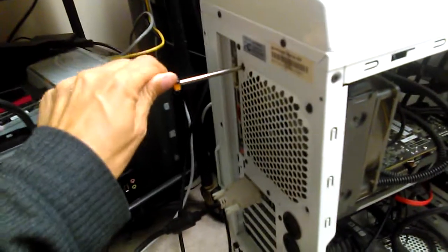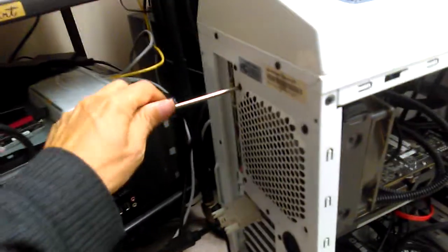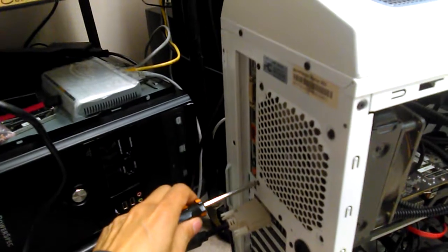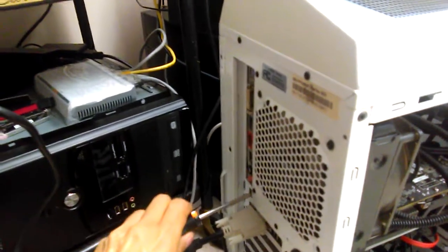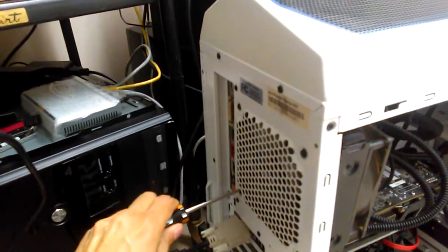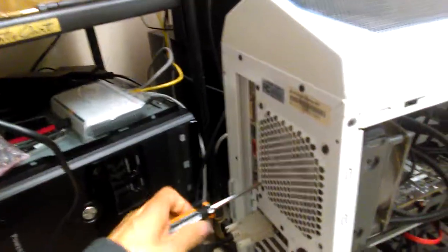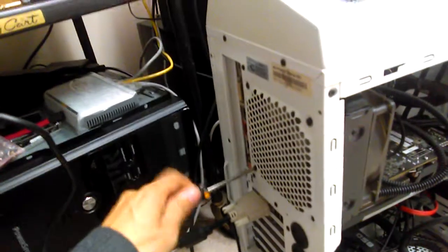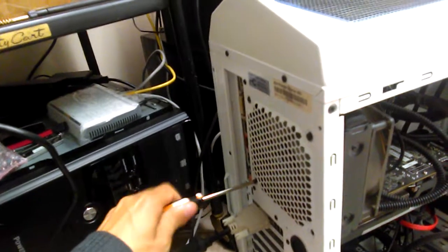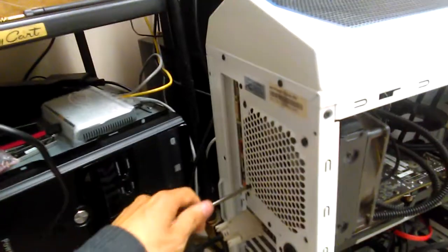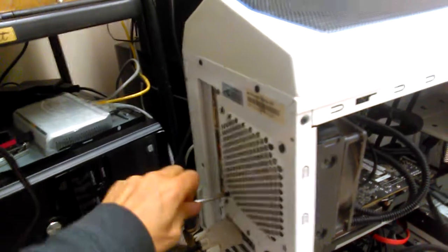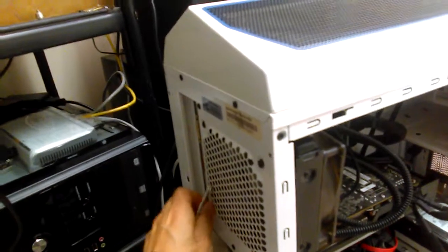I don't use soap or chemicals, but I do make sure I let it dry. You want to make sure you let the fans dry. I also clean heat sinks that way too, believe it or not. But you might want to make sure that you let the fans and heat sinks dry, because electricity and water do not mix in physics. So it looks like it's just probably 3 screws that hold this heat sink slash fan.